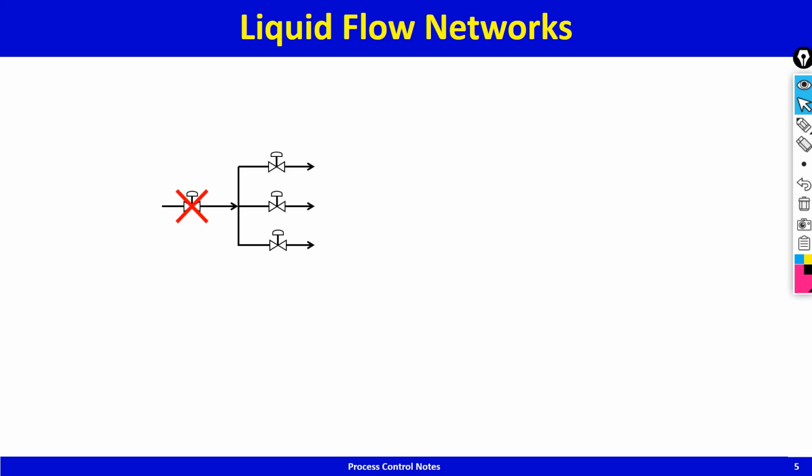And on each of the other 3 independent valves you can have a flow controller, and each of those flow controllers has its own set point, F1, F2 and F3, and therefore the degree of freedom for this process is 3. And as shown in the control system, the specification variables corresponding to these 3 degrees of freedom are flow 1, flow 2 and flow 3, those 3 set points.